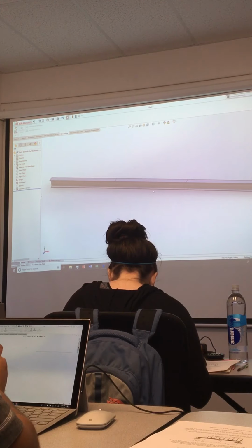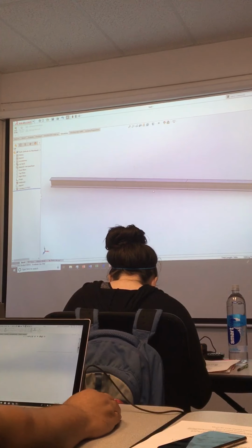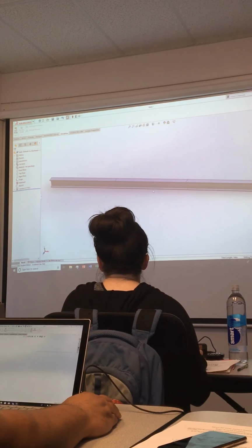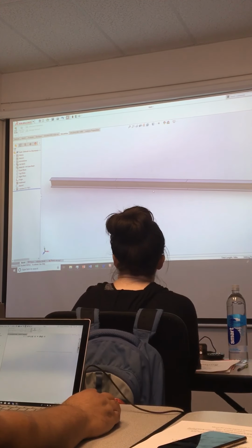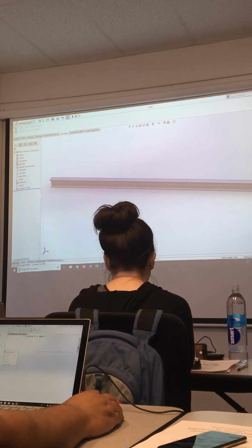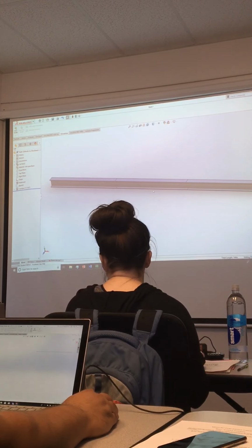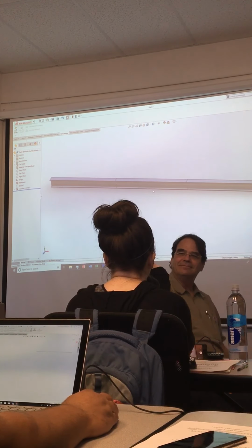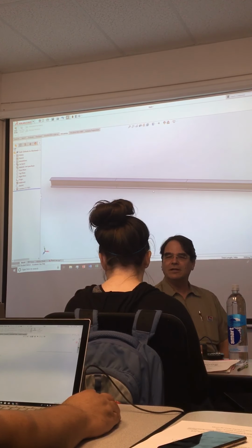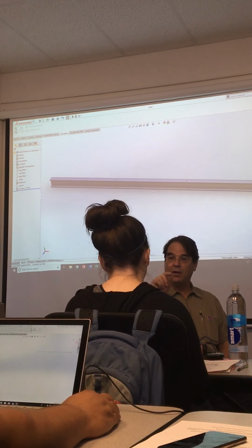So wasn't that a hard edit? You guys can accuse me of making this model hard because instead of drawing a line, you had to draw 3 lines. It's 3 times as hard. I cannot refute that. However, it doesn't take 3 times as much work in creating the weldments, right? Because you just have to add them to the same. You just go in and edit the weldment feature, and then that'll add to it over here.